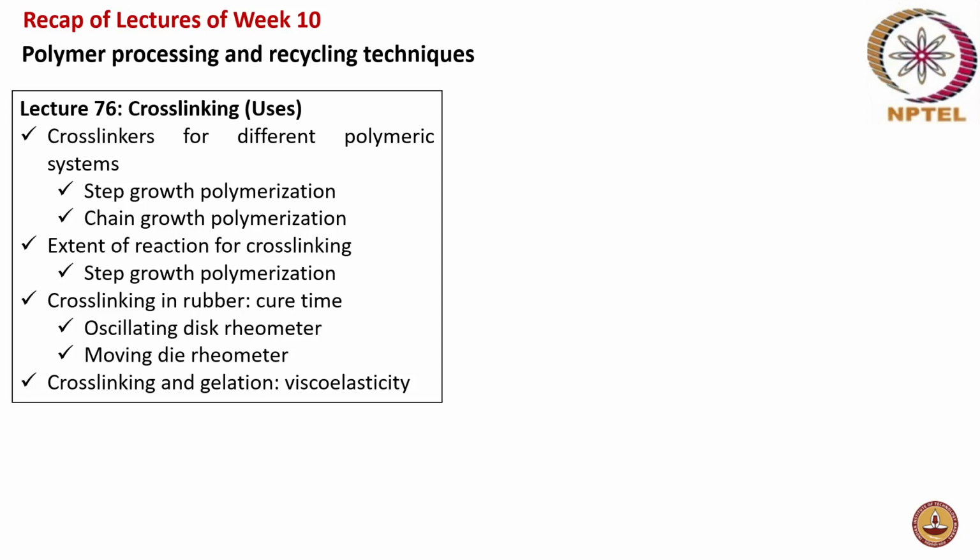moving disc rheometer, the flow behavior is analyzed. And then cross-linking and gelation, the concept of viscoelasticity of cross-linking and gelation, that is the change in dynamic properties. So how the modulus, the storage and loss modulus vary over time upon gelation.